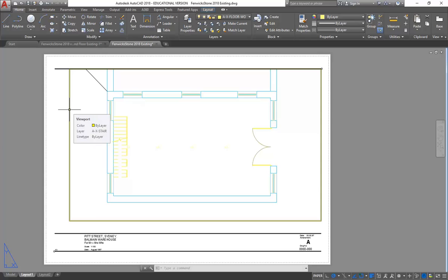Oh, not that much detail, no. So just label the new things that are part of your design. So all I expect is, say, if you've got new timber frame walls or new partitions, just label those as timber frame or stud, timber stud walls with plasterboard lining, or if they're wet areas, timber frame walls with fibre cement lining with tiles over or something like that, or fibre cement and tiles, however you want to label it.